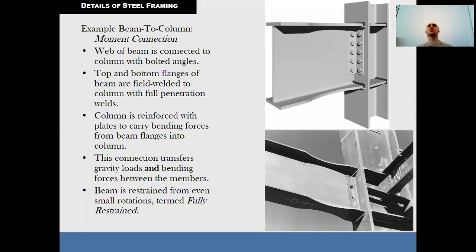For low-story buildings, such as portal frame structures, haunched moment resisting connections at the eaves and apex of the frame are almost always used to provide increased connection strength.